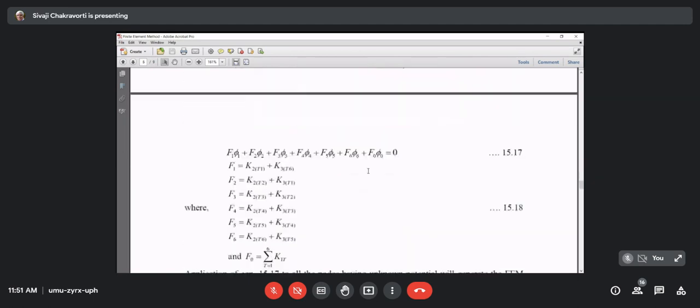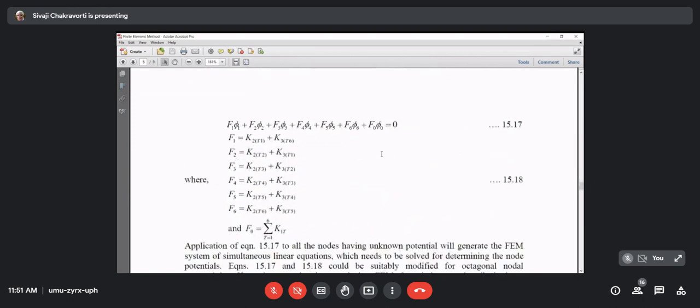So when I have written the equation in details, you see phi 0, the last term here, this will have 6 terms, so it is written as F0 at the bottom, summation of K1t, and t varies from 1 to 6. That means it will be K11 plus K12 plus K13 up to K16 because phi 0 belongs to all the 6 triangles.